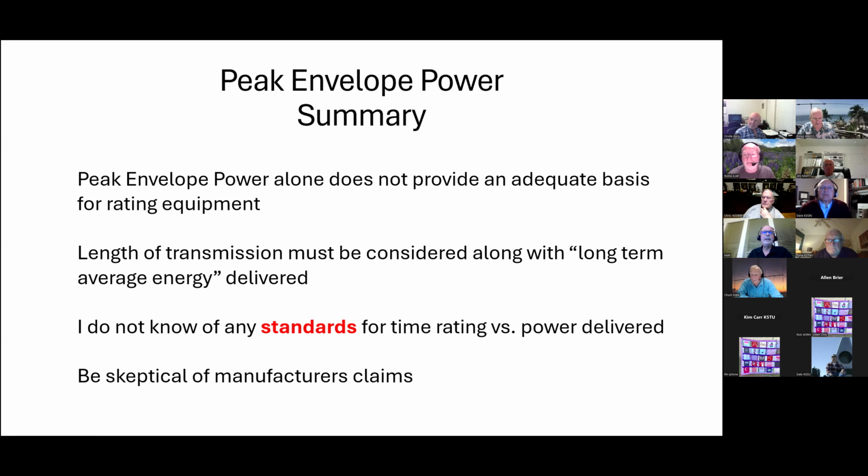Some of that old gear was rated at the input power and not the output power. I had a buddy who said, well, man, I got a 1 kilowatt tuner, why am I having troubles with it? He was arcing it over. I said, well, that's 1 kilowatt input, not output. With class C efficiency somewhere in the 70% range, right? Well, he was running it behind an SB-220, which was putting out, I don't know, 1,000, 1,200 watts, and it was arcing over.